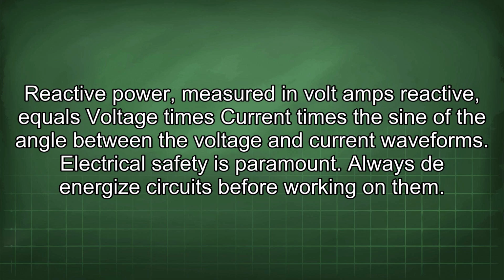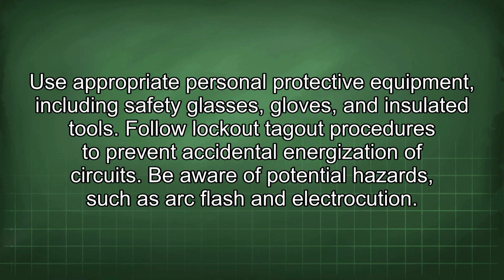Electrical safety is paramount. Always de-energize circuits before working on them. Use appropriate personal protective equipment, including safety glasses, gloves, and insulated tools. Follow lockout-tagout procedures to prevent accidental energization of circuits. Be aware of potential hazards, such as arc flash and electrocution.